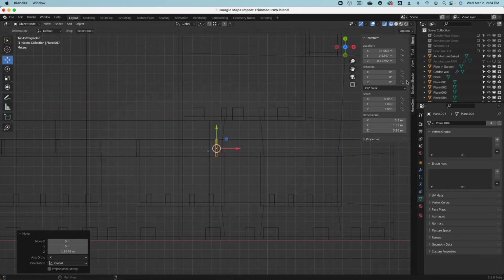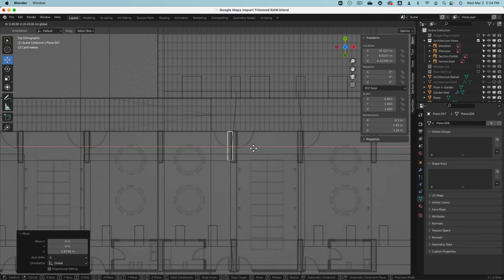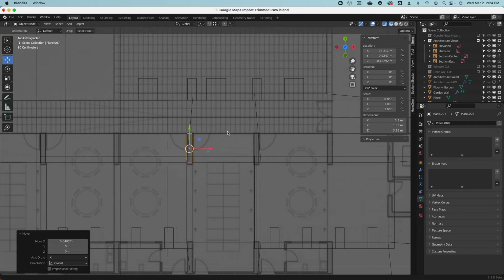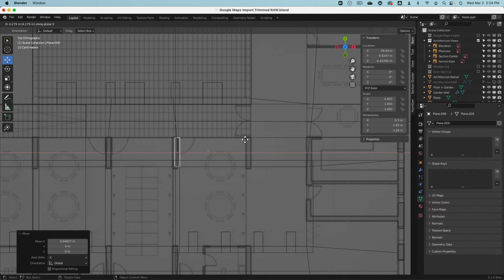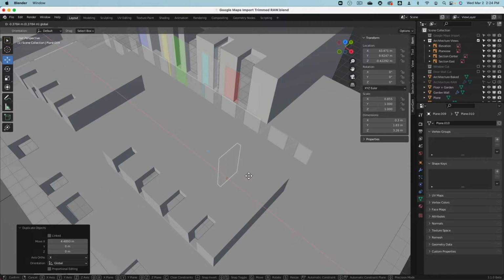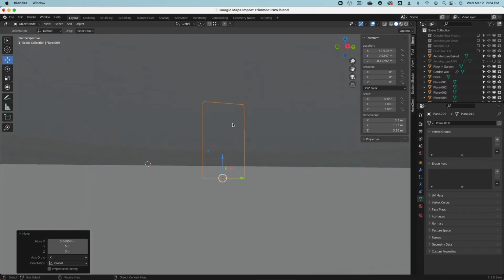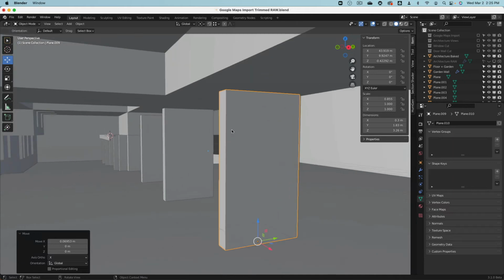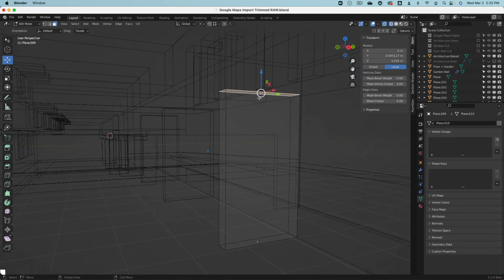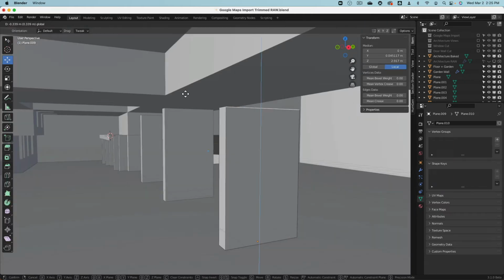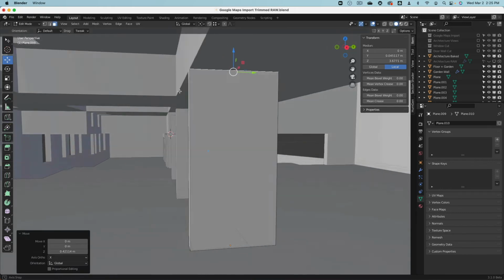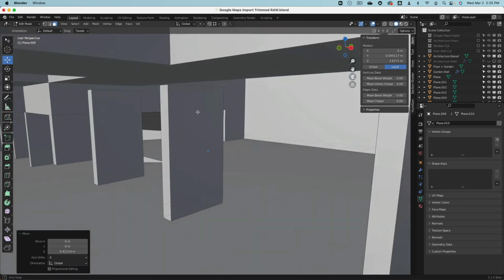Then here, this one, Alt D and X, move up, move down. Top view, architecture view. So U, was this a clone? It's a clone, so no clone. Shift D and X, Shift D and X. Move, snap. And edit mode, Z, select the top face, Z, go back out of edit mode. Oh yeah, there, this works.